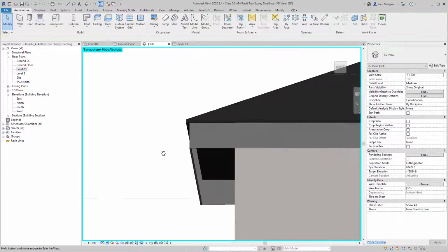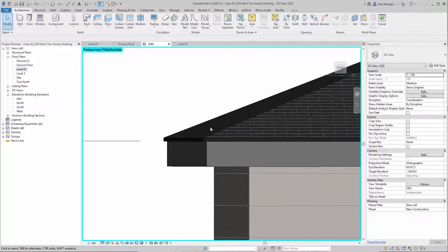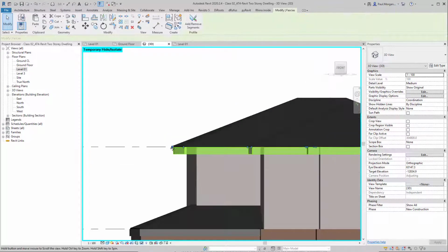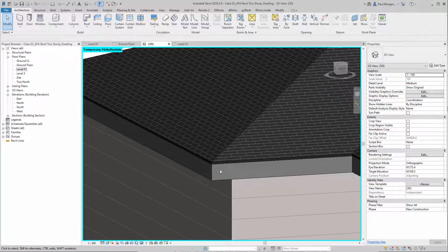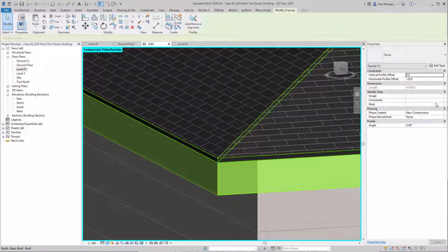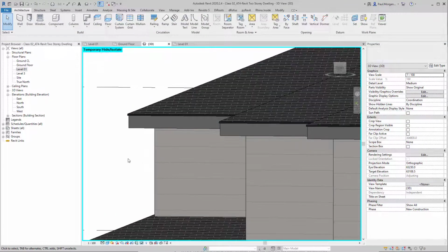And that makes sense, right? Because your fascia board does something like this, and then we put our gutter here, so when our water comes off the roof, it goes straight to the gutter, not onto a fascia board, onto a gutter, as an example. And maybe we don't need to be that far back. We only have to offset it, say, minus 20 mil, just slightly. Or 25, I reckon, actually. Actually, got to take into account the fascia thickness, which is 19 mil. So 19 plus 20, so we'll say 39 mil. Okay, so it's offset 20 mil back. So it'll look something like that.